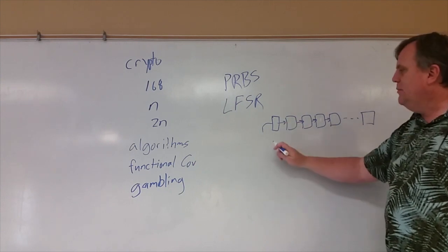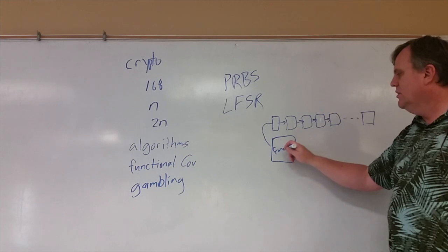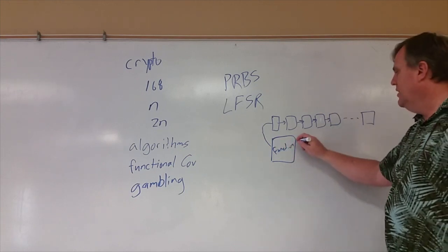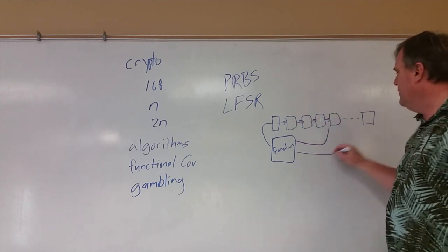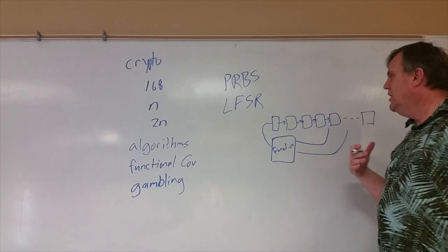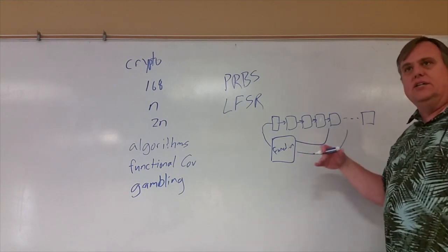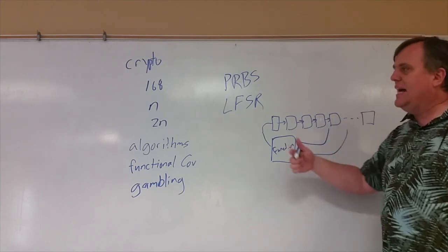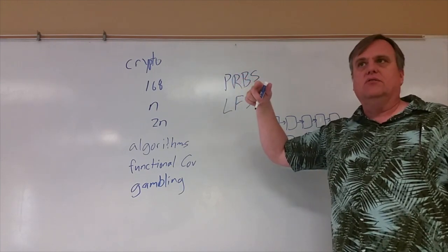The new bit that's coming into it is the product of some function, which is almost always XOR. Right? And it pulls in from what are called taps. And they try to pick the tap locations that will guarantee the maximal repeat, how long till it repeats something.